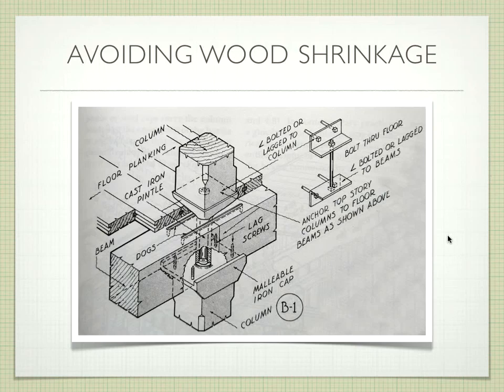If we had this set of beams running, and we put the next column just on top of that set of beams, or on top of the flooring, this beam and flooring would shrink, and that whole column would shrink, causing the floor to dip in that particular place. Does that make sense? Versus a masonry wall that's fixed. Okay, if we have the building where it's all wood frame, there's no masonry walls, we don't have to worry about it as much. But in this context, we need to worry about it.